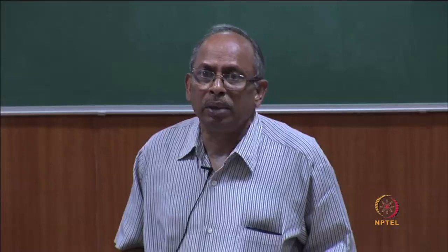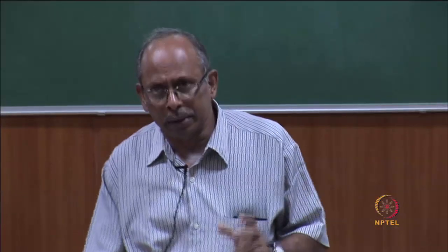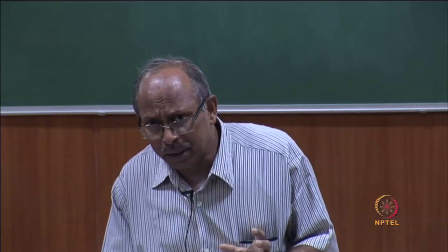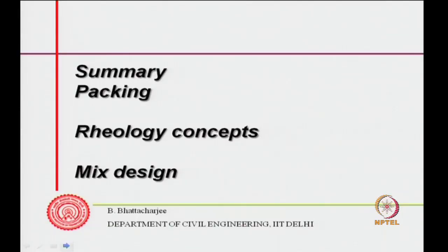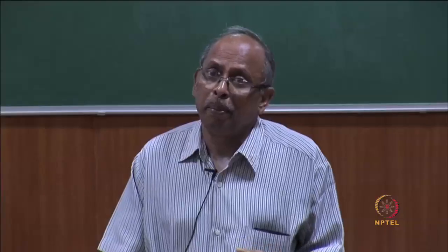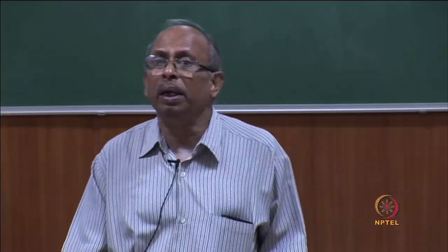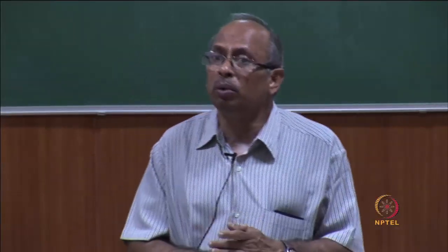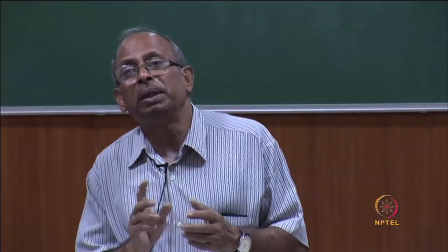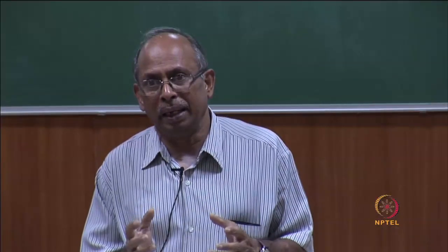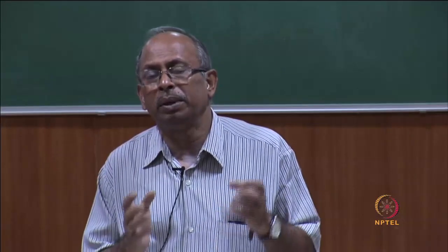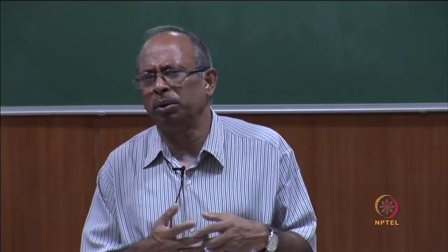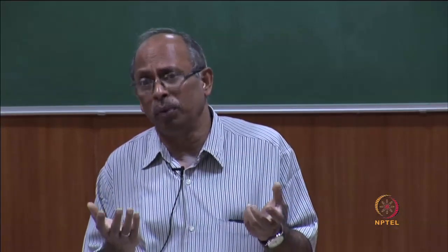So, I think with this our discussion on mix design is finished. The summary of this particular lecture is packing, rheology concepts and mix design. But if we look at the whole module summary, then what have we looked into? First of all, we looked into the basic principles of mix design. If you recall, we had a diagram, and we said that strength is a function of water cement ratio; most of the mix design procedures follow that.